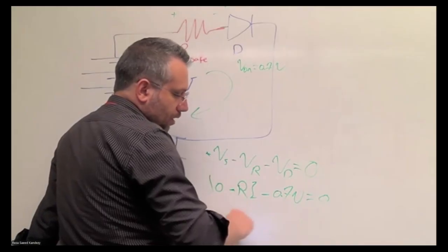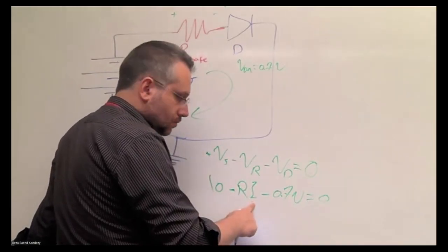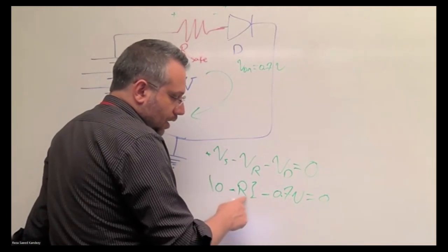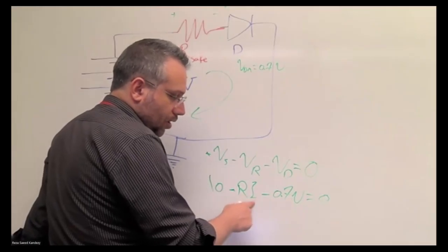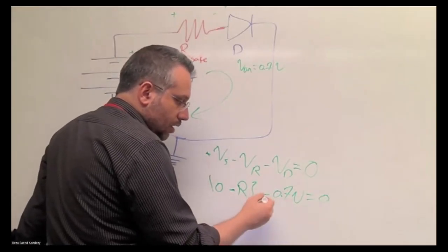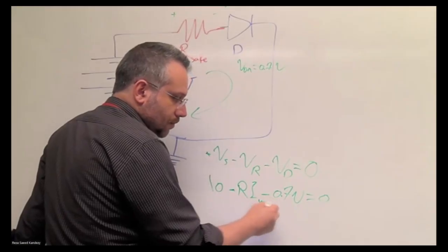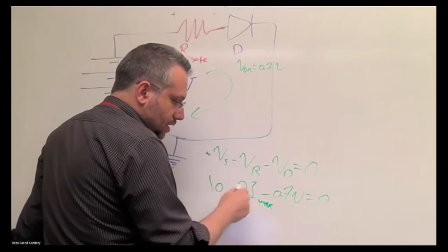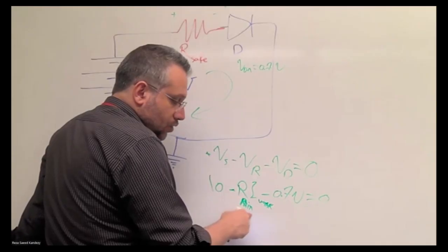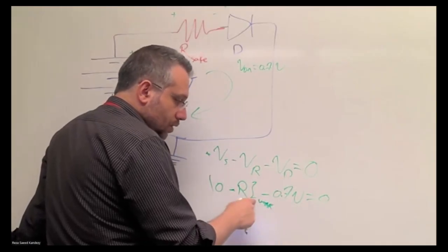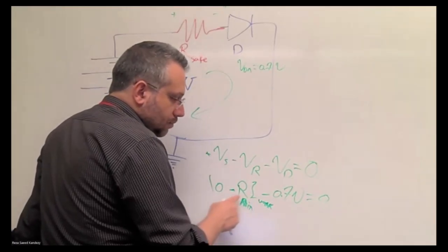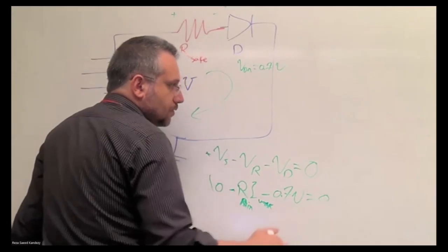Now, we want to limit the current to the maximum current. These two are constant. So what limits that? As much as we increase the resistance, the current goes lower. Worst case scenario, the boundary is that the current is the max current. So that means this is going to be the minimum resistance we need. Worst case scenario, we do not exceed the max current. So what would be the minimum resistance here using this formula?